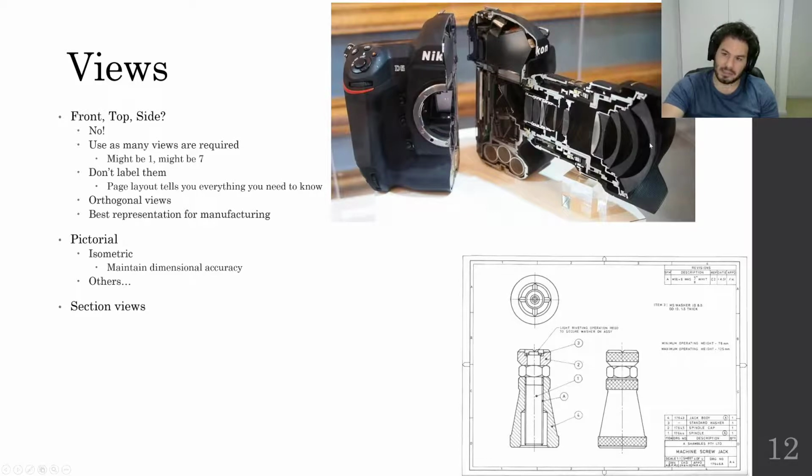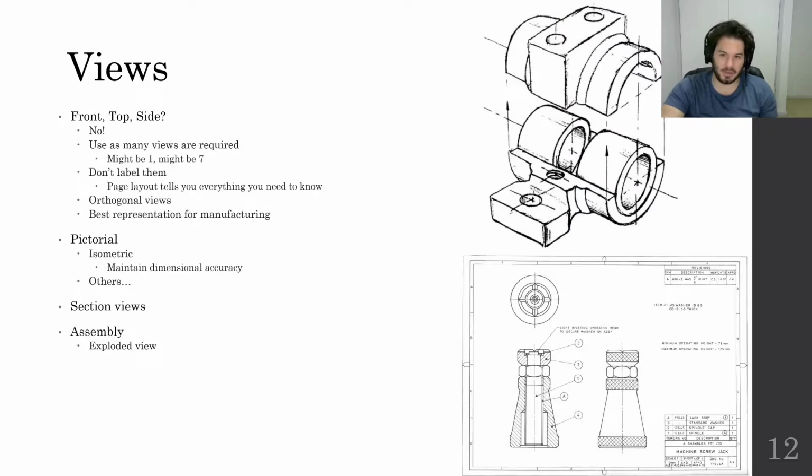Anything that's a cut face, so this is a cut face, that's been cut in half. All of this has been cut in half. Anywhere you've cut gets this hatching. Anywhere you haven't cut, like in there, doesn't. So it would just be a normal surface that you'd look at, and it doesn't get the hatching. So section view is fantastic for showing internal geometry. There's an argument to be made here that if you were ever to use a hidden line, you should have just used a section view instead, because they're better in every way. They take longer to draw, but they're very, very good.